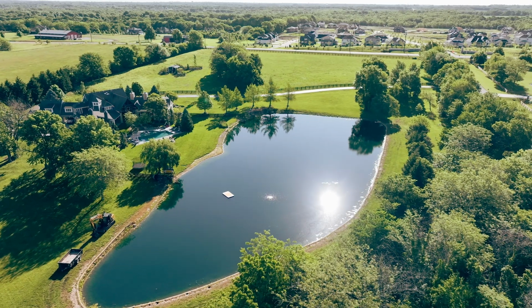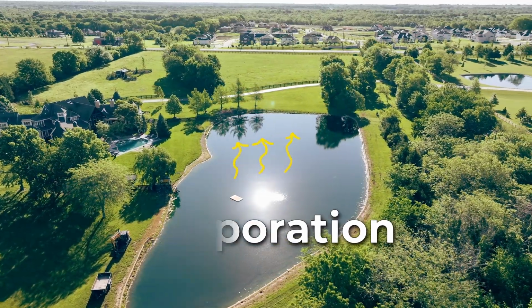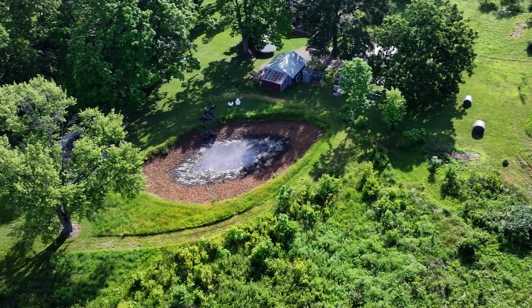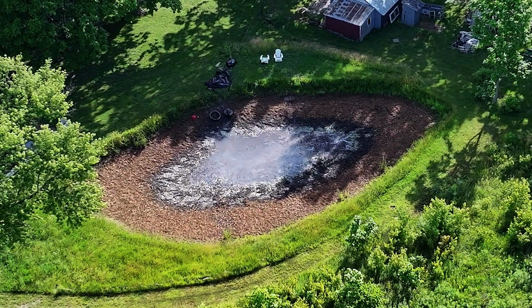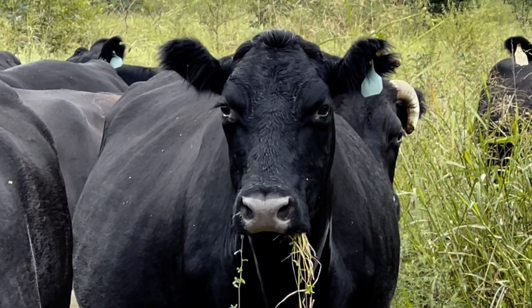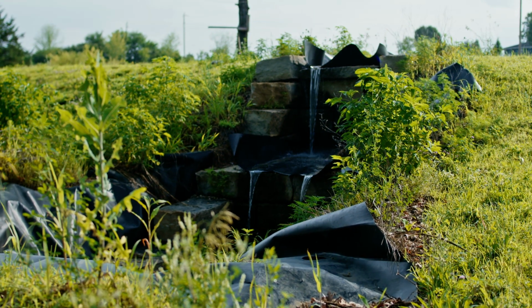The next thing we're going to be looking for is how much evaporation this pond is going to be subject to, and what other factors might cause the pond's water level to drop. Some of those might be seepage through the natural bottom of the pond, or things like irrigation or cattle, or any other source that's pulling water from the pond. And as long as there's a good balance between the water coming in and the water going out, then we know we're good to go for that specific site.